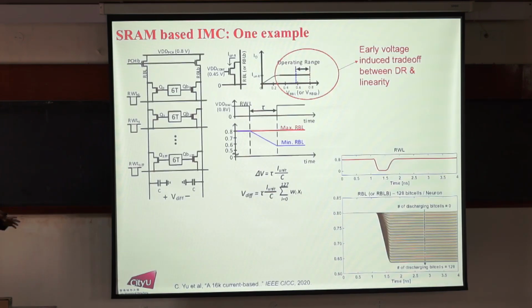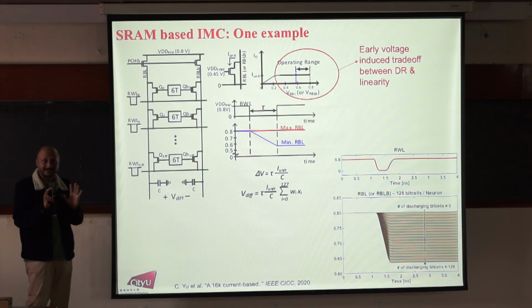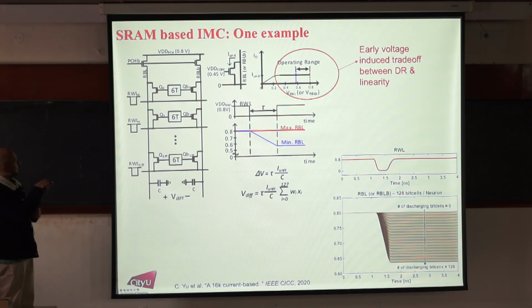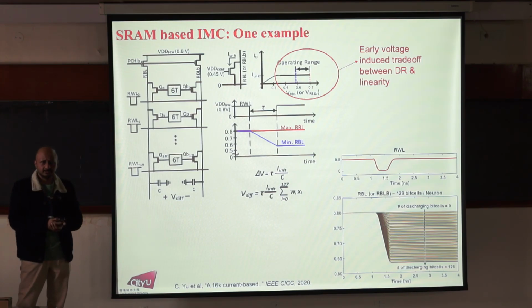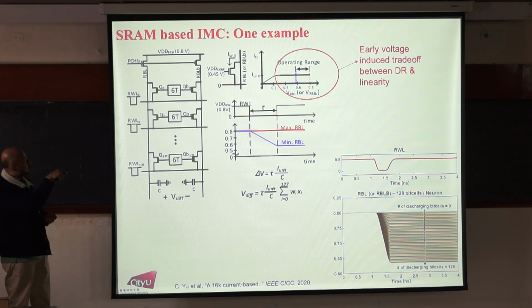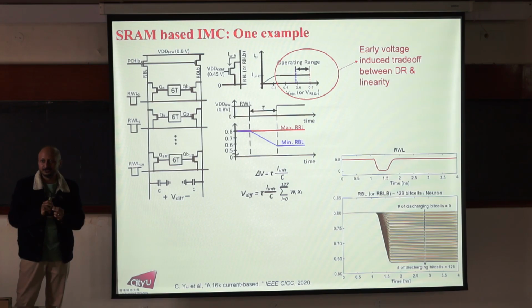Just to give you an example, this is sort of a simulation. This will clarify hopefully a lot of things. Now see what's happening. This 6 transistor cell is storing the state. This access device is the one that is discharging this bit line and bit line bar. So think about it. The gate of this device goes to a fixed voltage depending on the power supply of your SRAM. So this kind of has a fixed VGS, so it's sort of acting like a current source. And it's going to pull out some current from this bit line. So our first order approximation is a current source, so it should be a constant current.